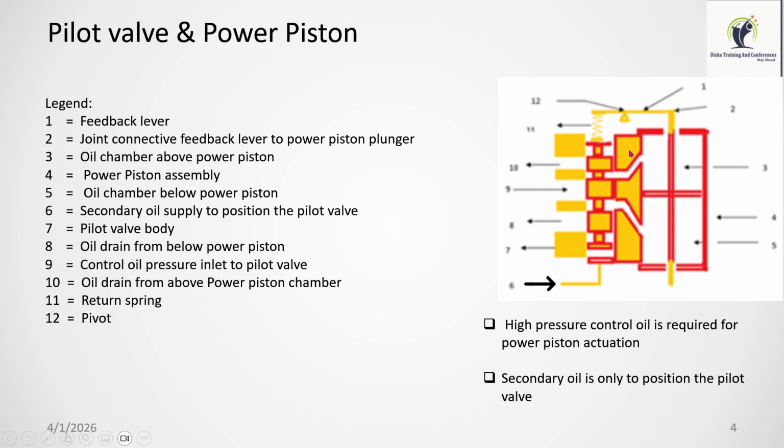Now, there is a pilot valve. You see, this is the pilot valve. At the bottom of it, the secondary oil pressure is connected. At the top, it is balanced against the spring force. This is the pilot valve, and this is the servo motor.